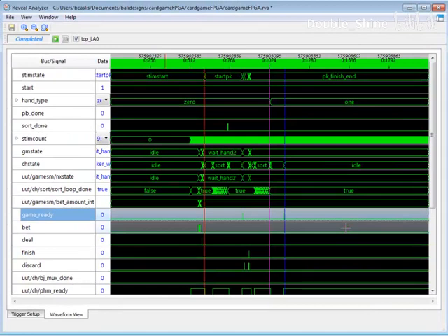So that's an overview of using the Reveal hardware debugger inside of Lattice Diamond 1.3, which now includes integration with the new programmer tool in Lattice Diamond 1.3 and some significantly increased speed-ups with the cable connection that allow you to both program the device within a couple of seconds and download the data within a second or so.